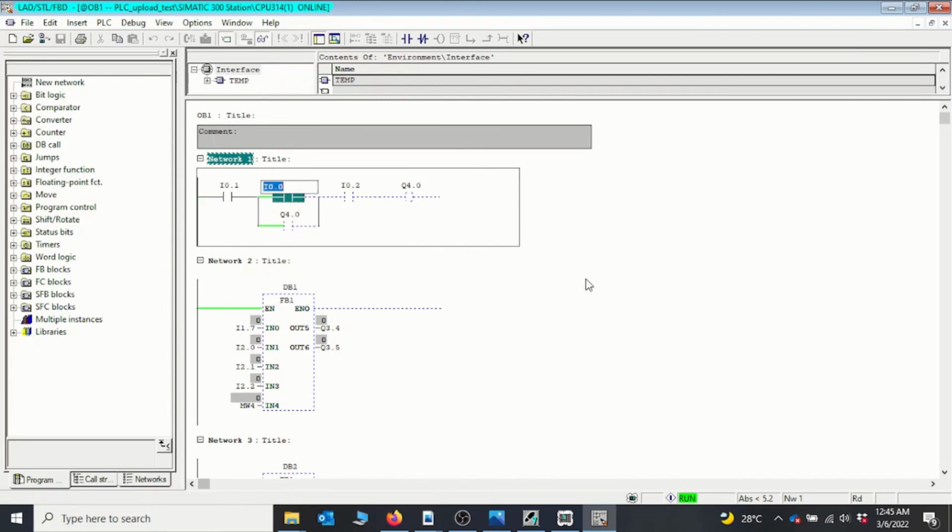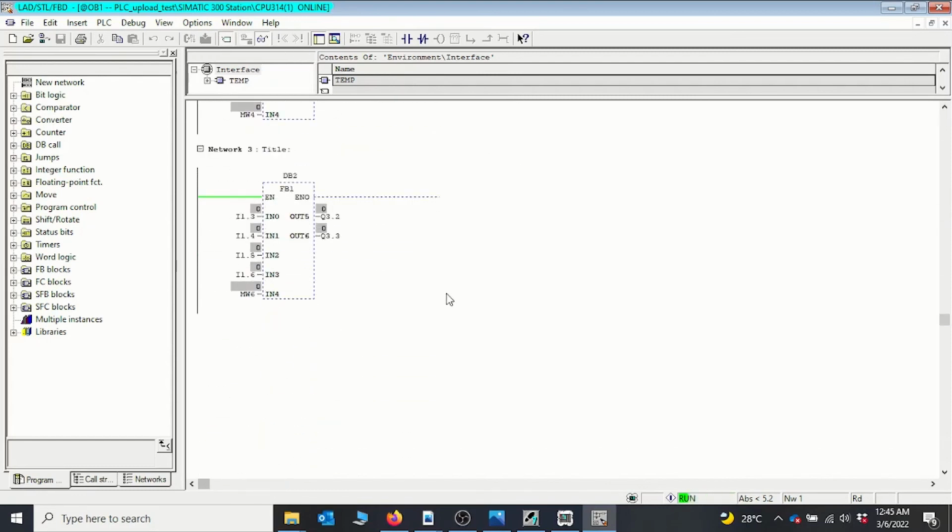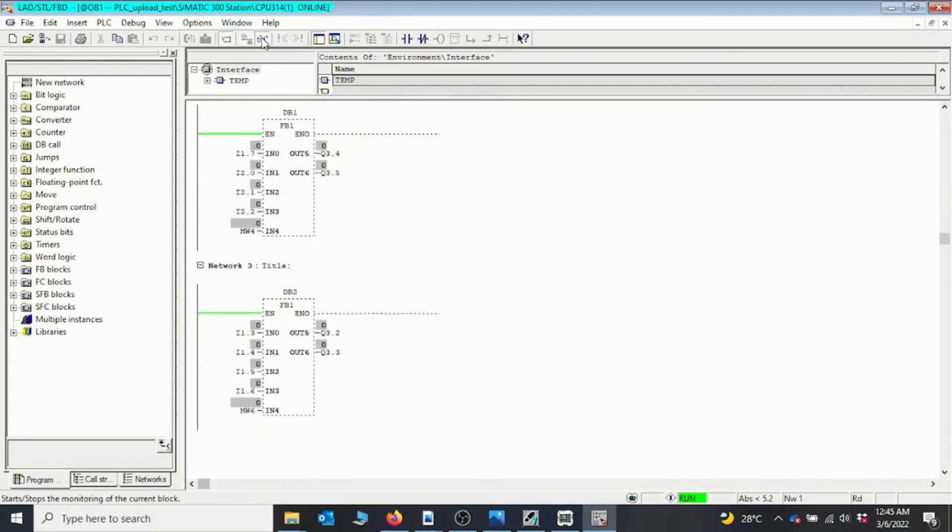So you can either add the symbol names by grabbing a manual from your existing electrical wiring and then identifying the actual IO inputs and then assigning the symbolic name yourself so that it becomes meaningful to you whilst you are troubleshooting. Okay, so basically we can see that we have all the blocks right here.